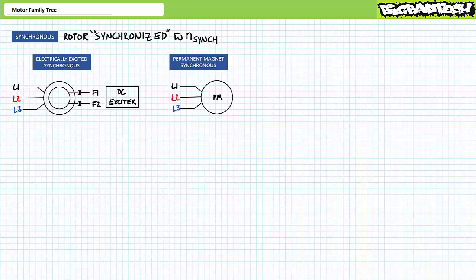As a summary of the process, the strength of the resultant magnetic field is proportional to the current flowing through the coil, and the polarity of the resultant magnetic field is dependent upon the direction of current flow. More current means more magnet, less current means less magnet.